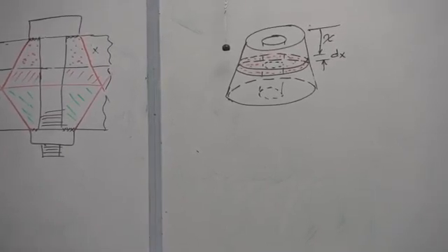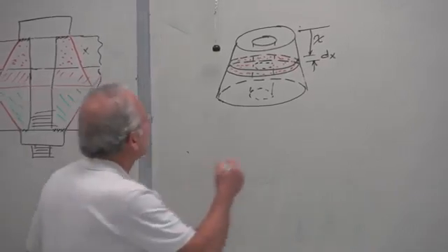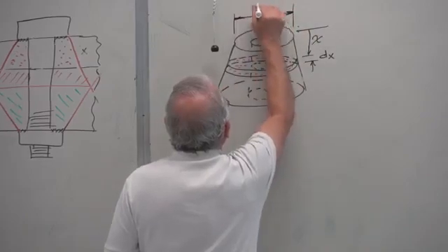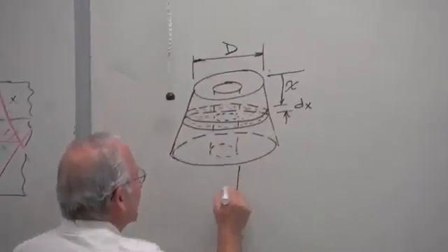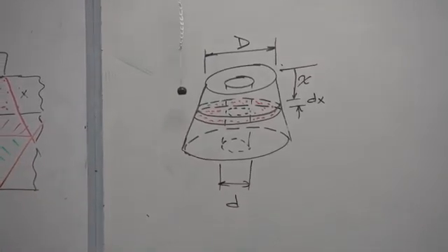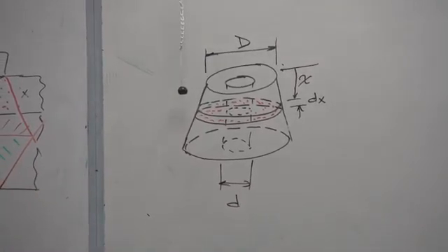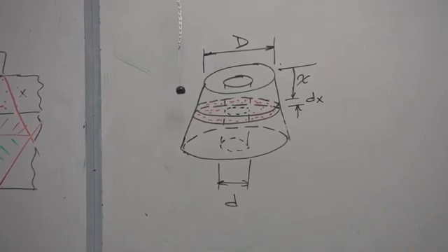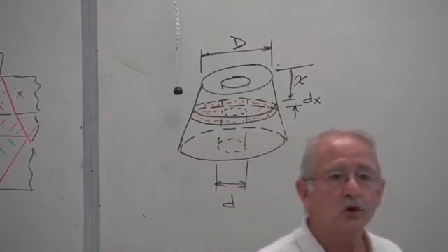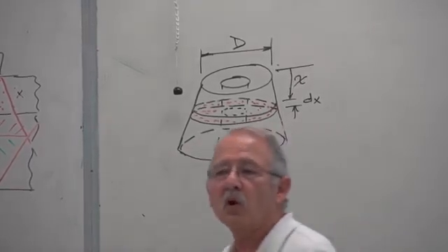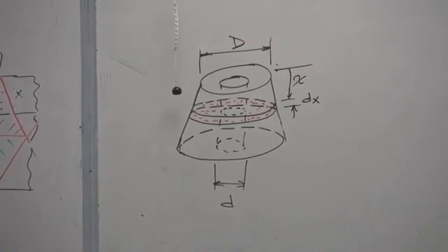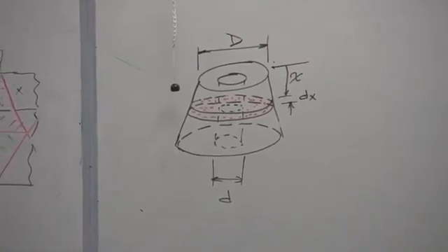One question that we will have to answer right off the bat is, what is that? This, of course, is the diameter of the bolt. Big D is essentially the diameter of the bolt head or the nut or a washer that may be used, any one of those. And it's very close to 1.5 times the bolt diameter.